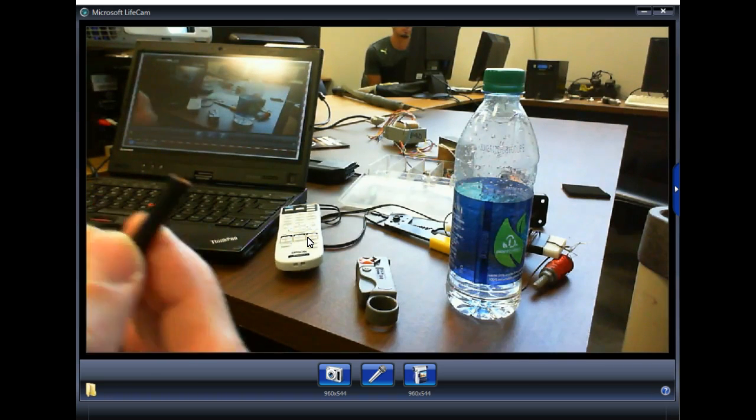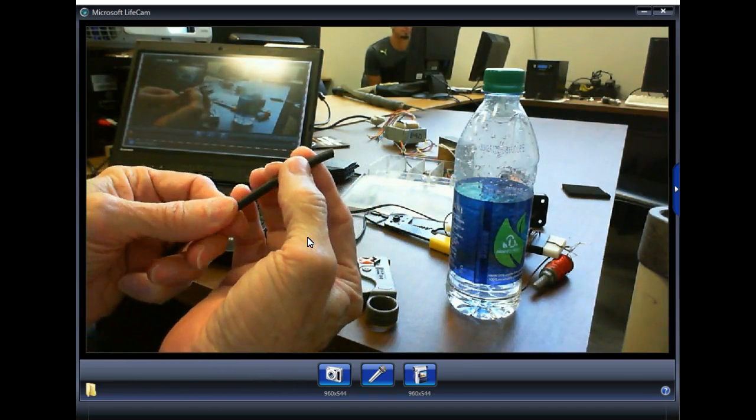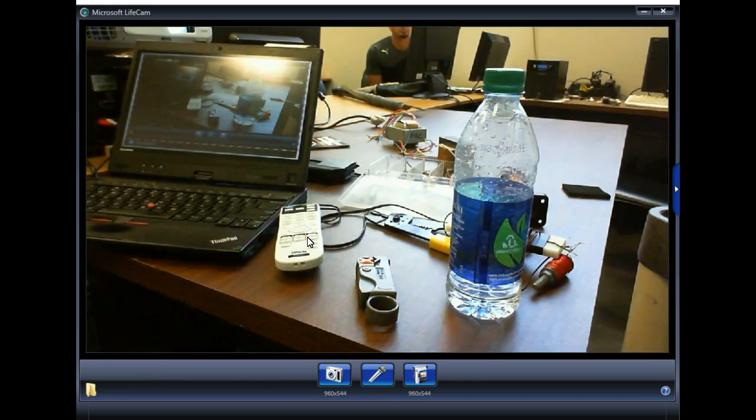The problem with cables, and of course we want to do this without nicking any wire. We call it scribing. We have scribes that we call glass cutters. You can't go out there and cut with a knife, but you can take a glass cutter and put a little scribe mark down that thing, and that sucker will break perfectly. Well, we have that same problem with metals, scribing metals, and that means putting little nicks in them. Once you put little nicks in a solid, it makes it real easy to break at that scribe mark.